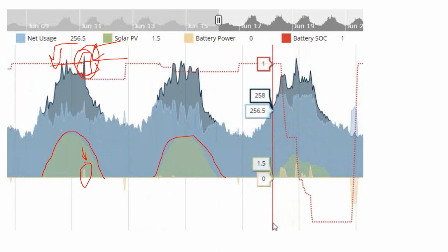And then on this other sunny day, what we're seeing is that solar does reduce building demand on sunny days. If we have a building whose peak demand occurs in the middle of the day, solar on a sunny day is producing in the middle of the day, and that's keeping that building demand much lower than it otherwise would be. The problem with demand savings in solar is not sunny days. And it's not necessarily cloudy days either. On an overcast day, your energy use in general is down. So what is problematic with solar is on partly cloudy days where the solar array is just not quite producing what it would under full sun.